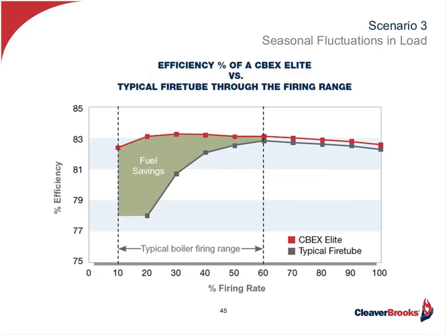In the slide that I showed you earlier, these boilers were most efficient at about 60% firing. But I've seen many boilers which are most efficient in the 80 to 90% range, and once they go under or above the sweet spot, they lose efficiency. Now the key is sizing a boiler to the load that it is intended to meet most of the time.